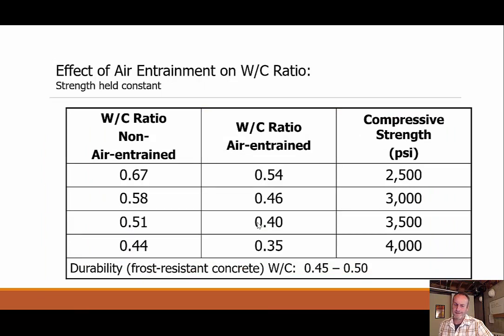So this slide is a little bit interesting. I think really all it's getting at is the fact that if we have air-entrained concrete, then it will not be as strong. And therefore, if we were to look at the water to cement ratios, if we had air-entrained, we need a lower ratio, meaning less water, than if we had a non-air-entrained concrete. But really, I think the takeaway here is just that if we have air-entrained concrete, then we need less water in our mix as well.